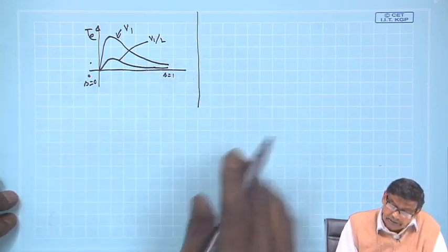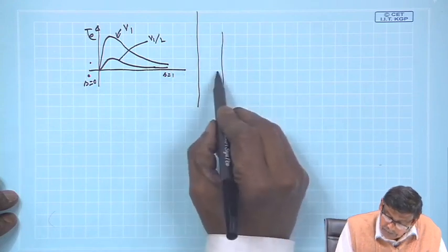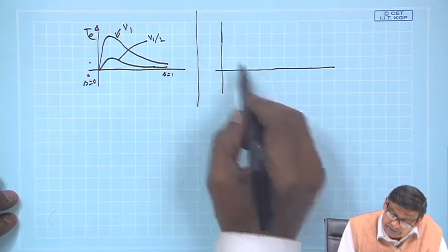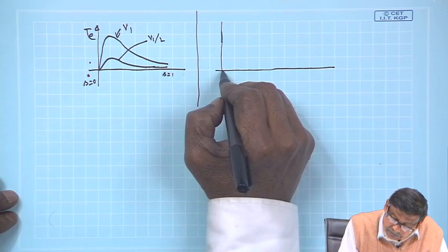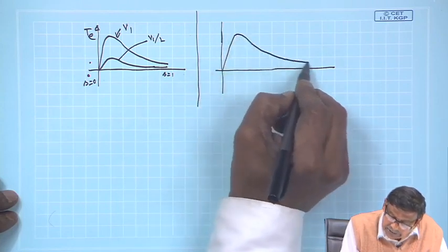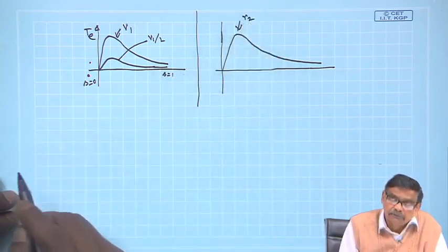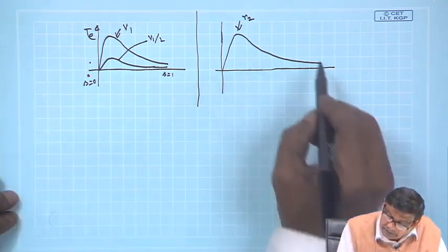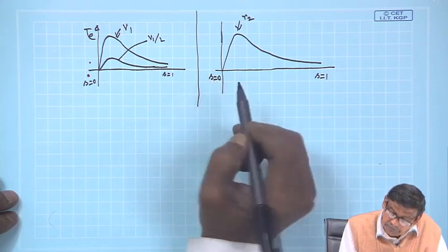Then we discussed about what happens if this rotor resistance varies. If rotor resistance is varied, how the torque slip characteristics changes. So, suppose this is the torque slip characteristics with inherent rotor resistance R 2, that will come as R 2 dashed with a constant multiplied. This is S equal to 1, this is S equal to 0.